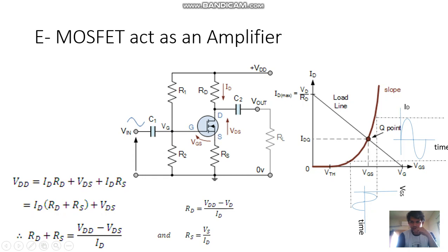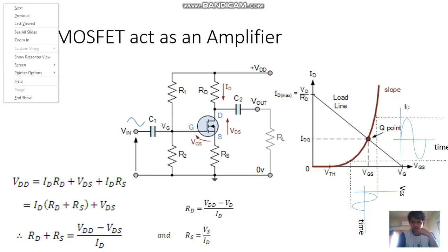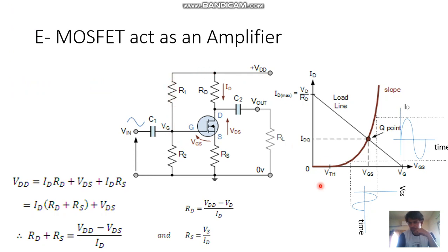Okay, then similar to that, here the minimum gate voltage Vg is obtained from here. So this is the input AC voltage applied at this point. If you project this onto the characteristics, you will get the output voltage. These are the transfer characteristics of the E MOSFET. If you project on this, you will get this voltage.